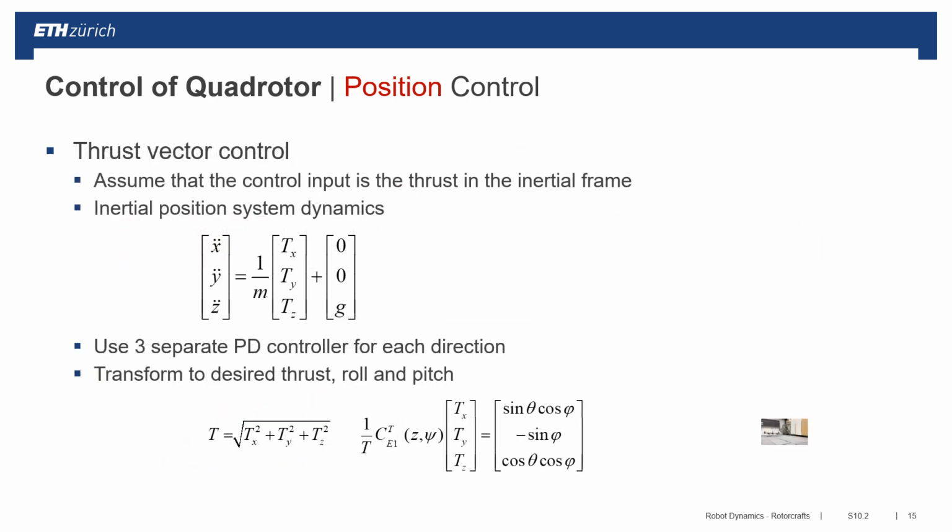Similar to the attitude control we have already seen before, the control in XY position is, in a first order model around small angles and around hover, fully decoupled in our dynamic model.